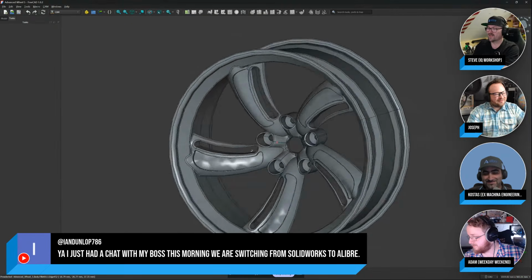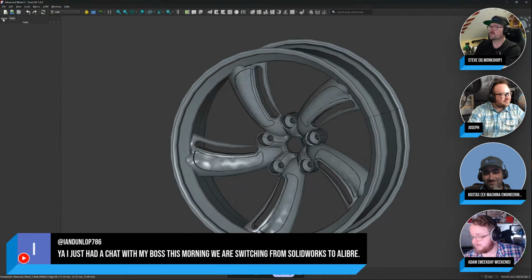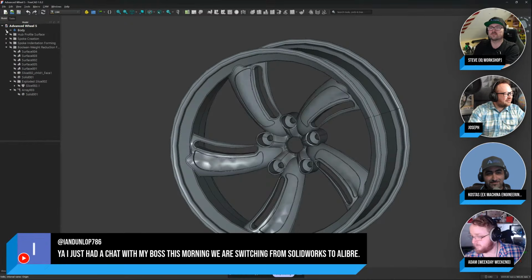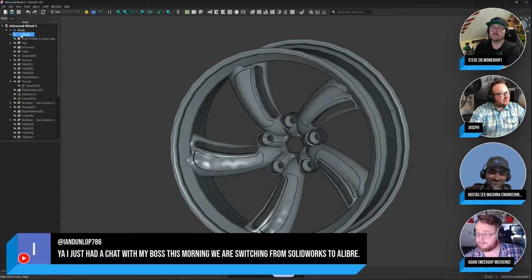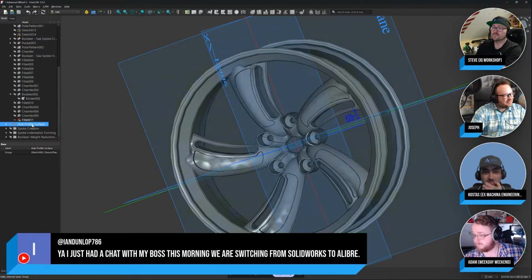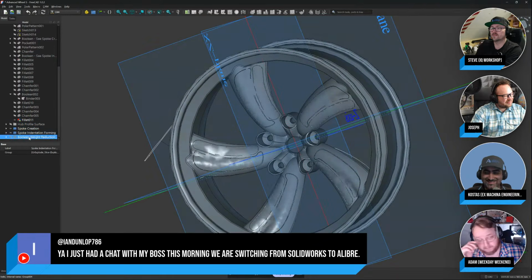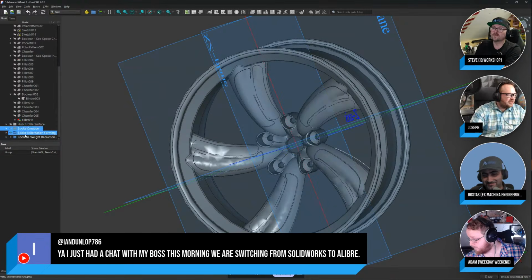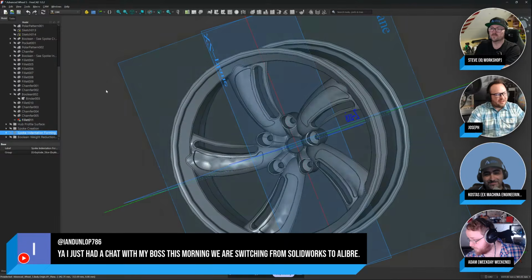I think where a lot of users might see benefits from switching is, and this is in no way meant to be a criticism of FreeCAD because I don't want to criticize all of the efforts that people have freely given to the world. When you go to the history tree, it gets a little bit complicated because I've had to create various groups in different places in the tree because I had to reference things from the part workbench versus the part design workbench, and switching some of the order of the items in the tree may not be very convenient if you have to revise your design in the future.